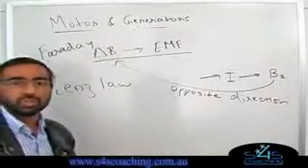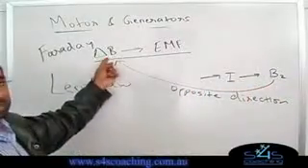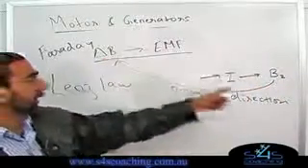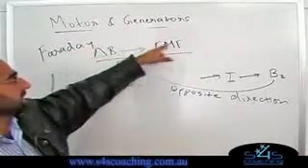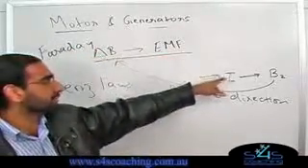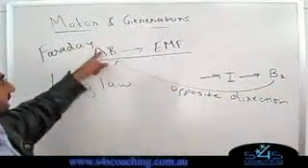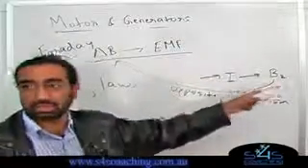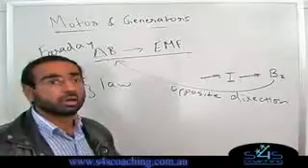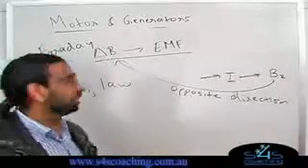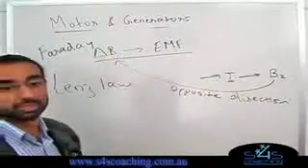If you think of the law of conservation of energy, if this new magnetic field was in the same direction as the original one, then it would add to it. So I would have a greater magnetic field, which means I'll have more EMF, which means I'll have more current, which means I'll have more of the generated magnetic field, which will then go back and add to this guy, and the cycle will continue endlessly. So therefore, to obey the law of conservation of energy, this new magnetic field has to be in the opposite direction to this guy.